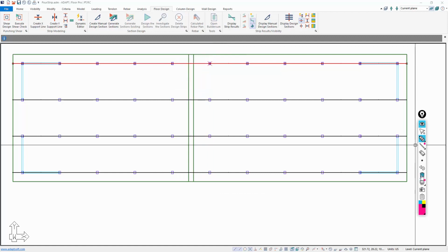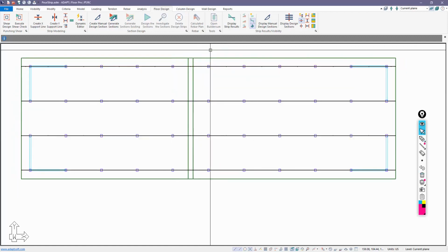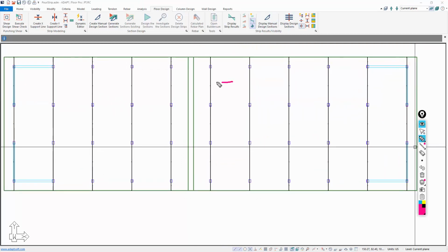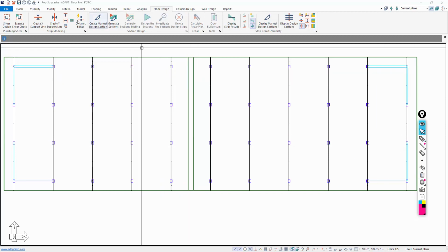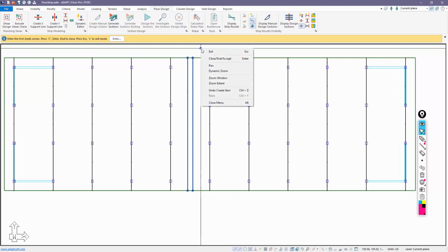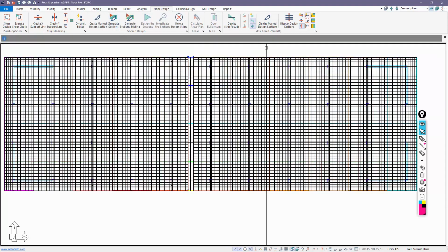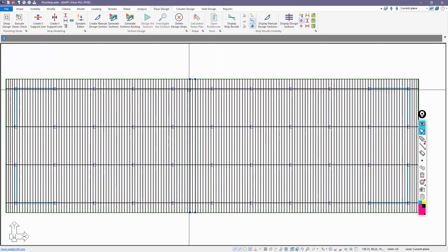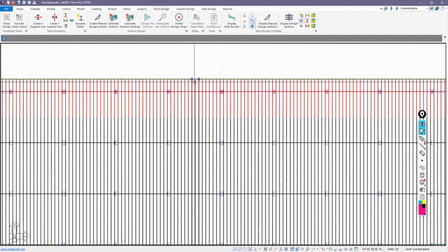So in the other direction, we have strips that are probably going to end up inside of the pour strip in the long direction. So we might want to avoid that. What we'll do in this case is just use a Y splitter, and I'll put a splitter along that edge and along that edge. Once I've done that, I can generate my strips. I'm going to turn off the strip generation. You can see there's the section cut inside the pour strip.